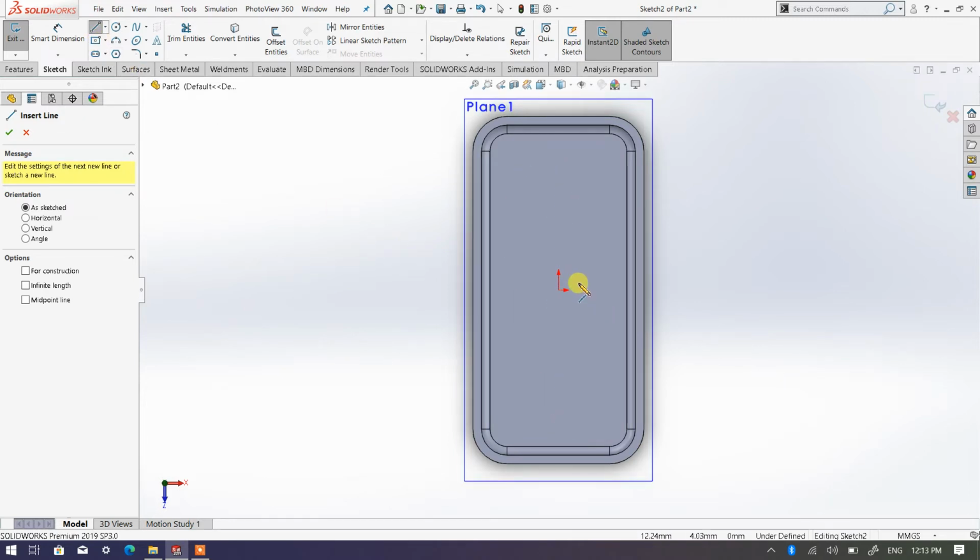If you still remember, I already showed you at the beginning of this video that in order to apply ribs on a 3D solid modeling part, the sketch line that we create is not necessary to touch all these edges.